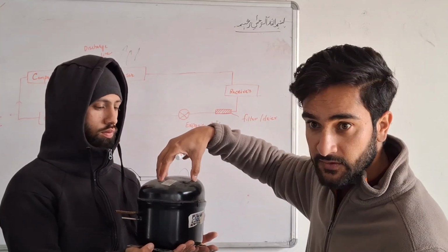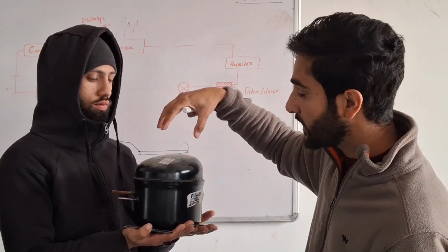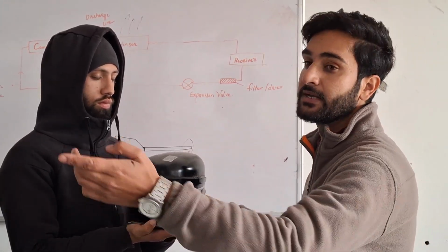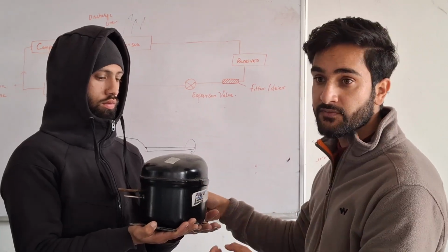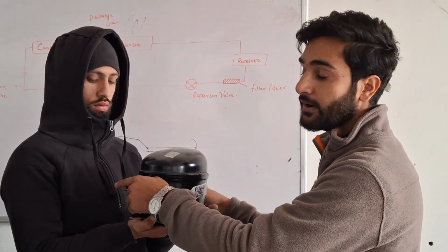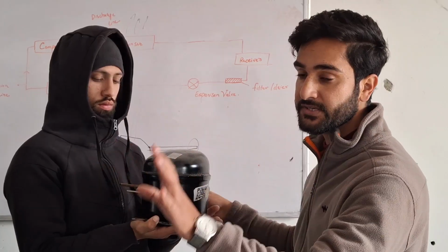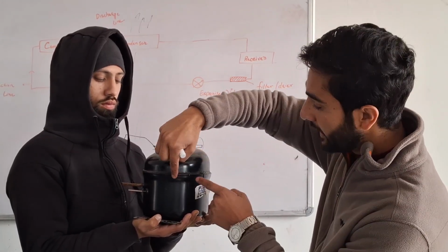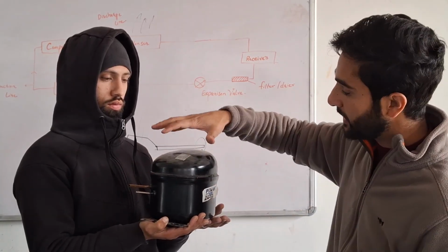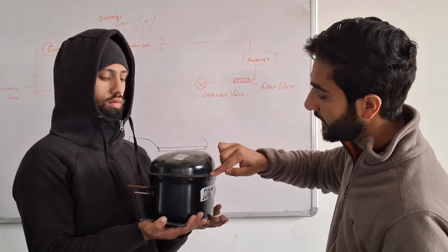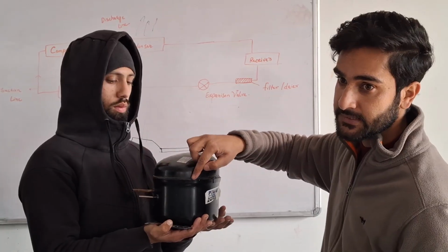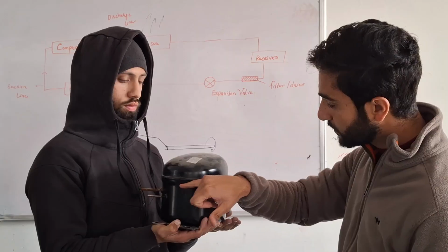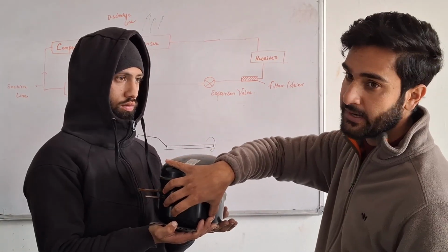So this is the heart of the refrigeration system, the compressor is the heart. It sucks like the heart sucks blood and pumps it out from another side. Similarly, it sucks the refrigerant from one side and discharges it on another side at high pressure and temperature. It is called hermetic because it has a dome shaped top and it is completely welded, so no leakage is possible. If the motor inside is destroyed, we have to remove this welding, and afterwards the motor can be repaired.